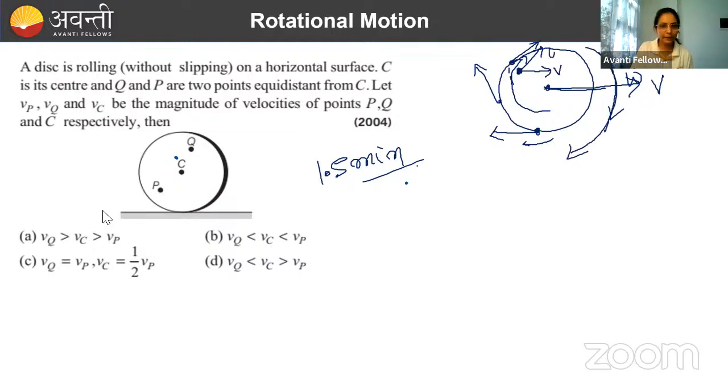For omega r, which distance will you take? This distance. If it is small r, then it will be omega r. So this point will have velocity v in this sense because of translation, and omega r in this sense because of rotation. R is the distance of that point from the center, right? So net velocity will be somewhere here, depending on the magnitude. Then here also we were given 2 points, O and P, CO and CP, like that is Q, I guess.